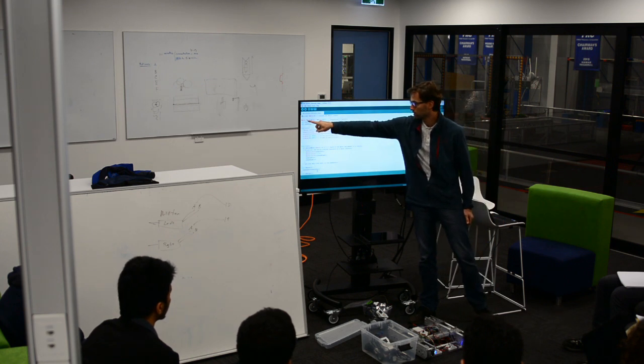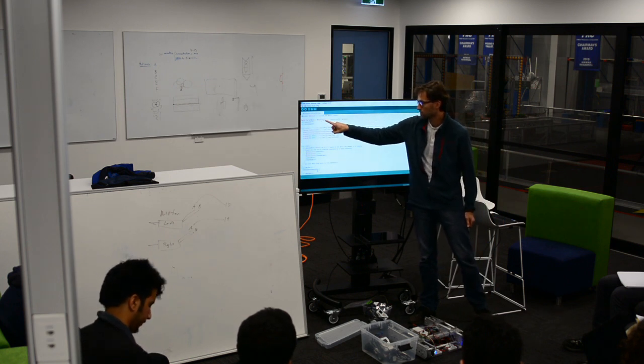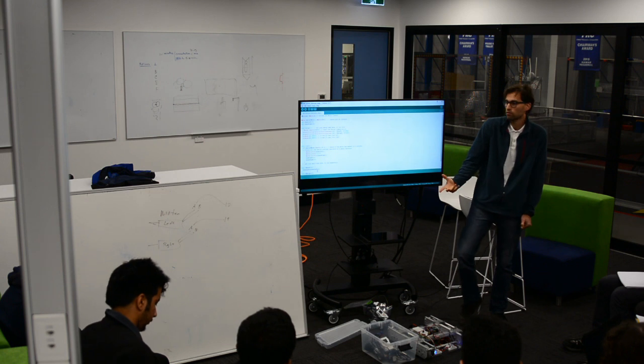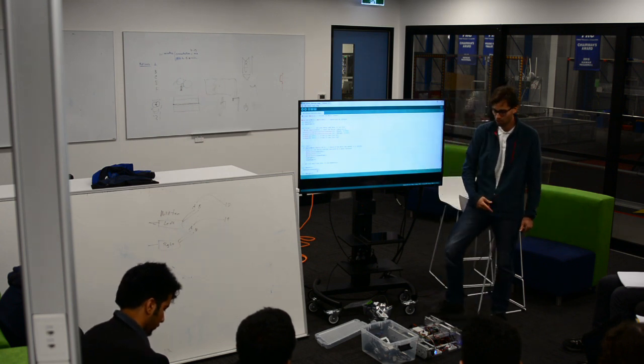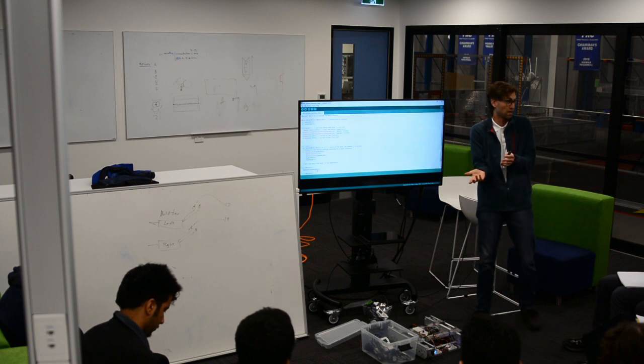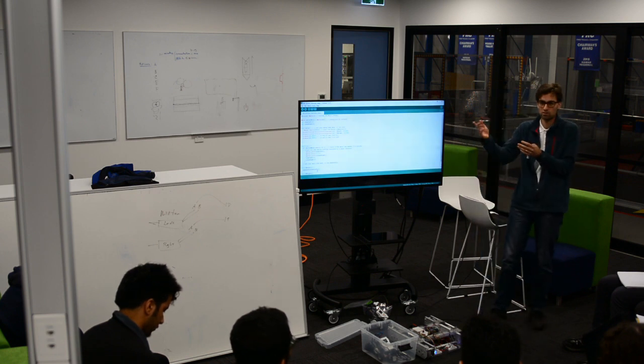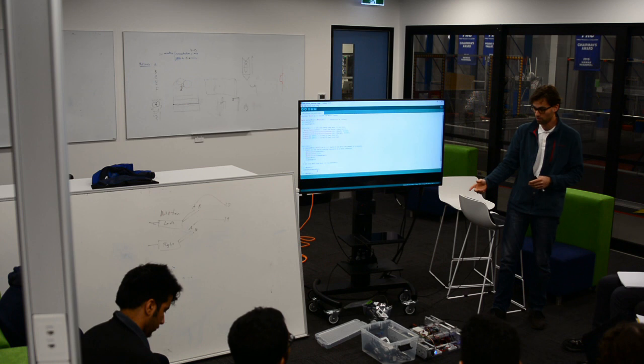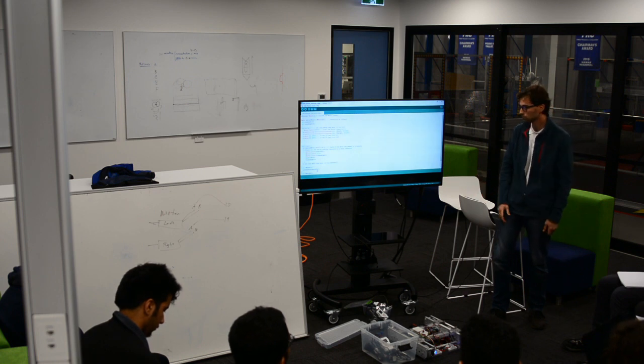This Metro will be a function called serial Metro that runs every 250 milliseconds. So every 250 milliseconds, what I want to do is just talk to the serial port, send some data to the serial port, and then for all the rest of the time, which is a lot of the time, right? 4 times a second I'm going to do this communication. All the rest of the time, I'm going to worry about controlling my robot.